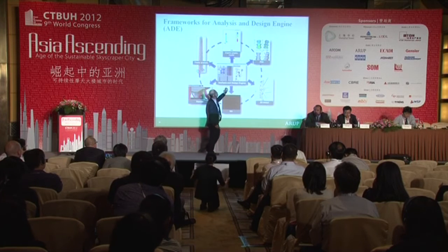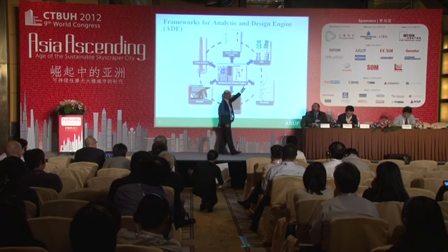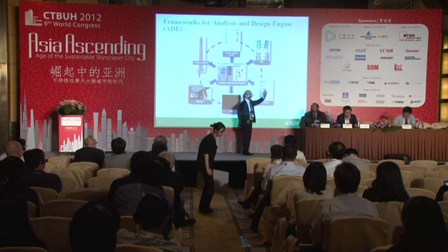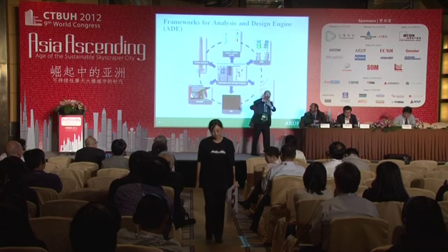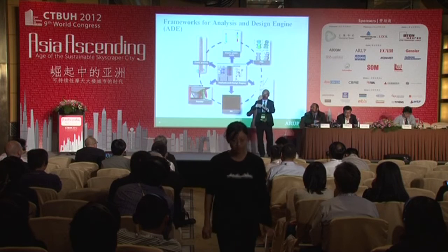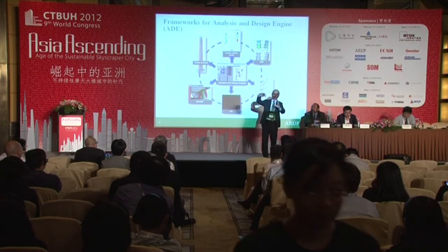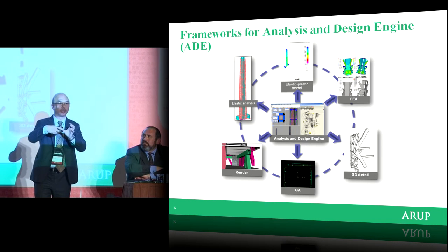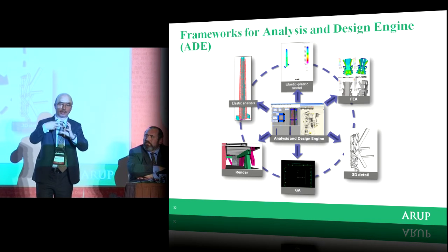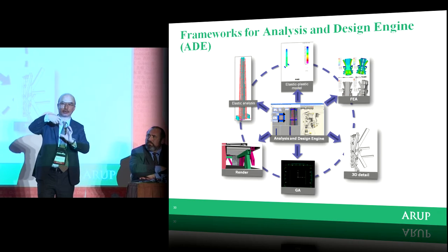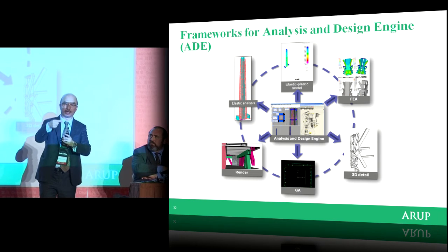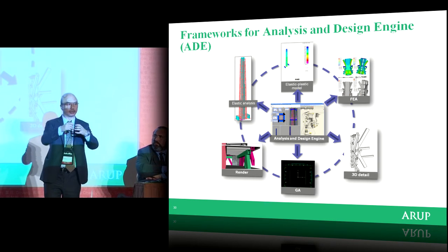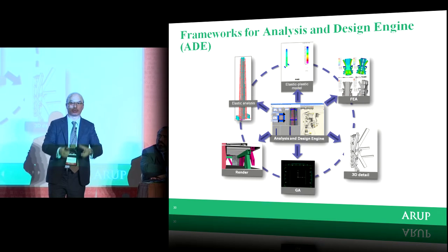But at the same time, more important, we create a connection model which is linked to the geometry. With the connection model, we have the bracing, for example. The bracing has a stiffener inside a column. If the bracing angle changes, the stiffener changes. If the bracing member thickness changes, the steel plate changes, and the stiffener inside the column changes as well.